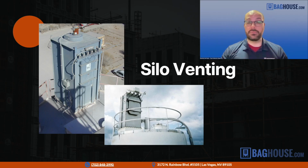So the most common setup is a big silo, where when the trucks or trains come and they blow the material in, or you have a big screw conveyor that drops material into a silo, on the top of the silo you have a bin vent dust collector. As the air is displaced, it goes through the filters and out the dust collector just like normal. Sometimes they have a fan that helps pull the air through. Sometimes they don't have any fan, so only the air being pushed in is what goes out through the bin vent. Other times it's both things. The air is being pushed in as well as the bin vent has a fan pulling out.